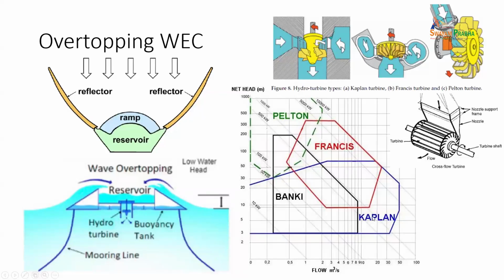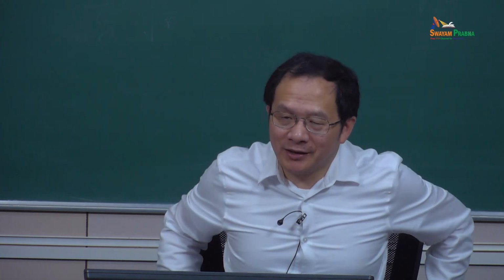So for this suggested range, there is an energy and head relationship, and between them there's a flow rate. Head times flow rate will be energy. This is why there's also energy in this figure. Is this clear? You try to see the relation of head and energy, right? So head times flow rate will be energy. Head and flow rate are the guide to help select the turbine. Overhead is just potential energy.